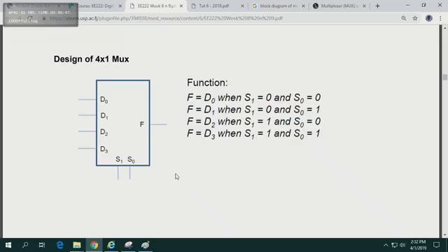But the technician only had a 4:1. You've been given a 4x1, and you need a 2x1. What are you going to do? How are you going to handle this? Discuss with your neighbor. Look at the truth table you want, you can draw the truth table. If you want, you can write this question down, it might come in your final exam.